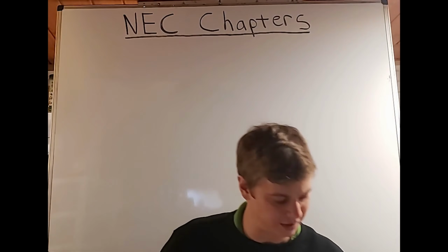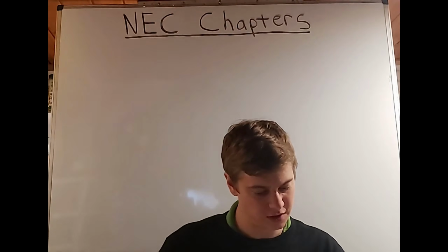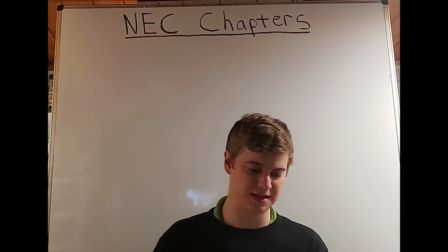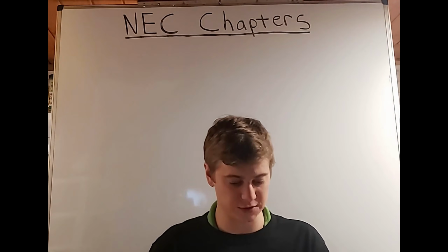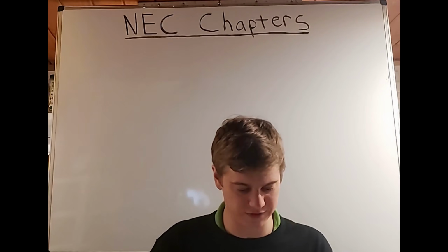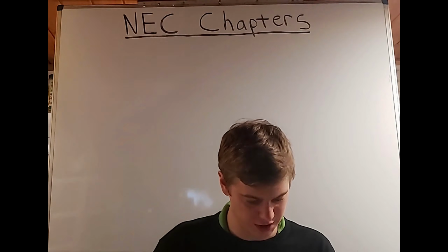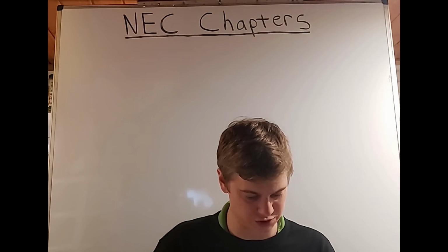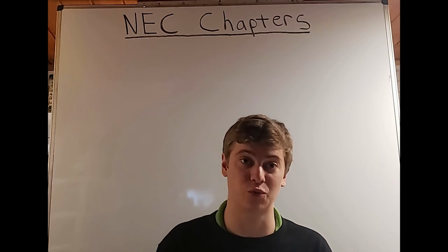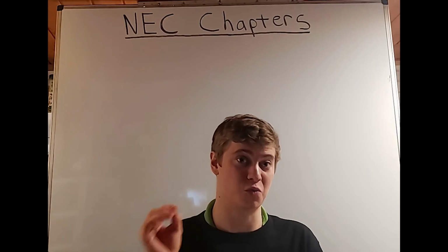Okay, Article 200.4, neutral conductors. We have A, installation, B, multiple circuits. Article 200.6, means of identifying grounded conductors. A says sizes that are 6 AWG or smaller, and it mentions the following means of identification. And of course, this is the insulation. Okay, so you can have: 1, a continuous white outer finish; 2, a continuous gray outer finish; 3, three continuous white or gray stripes along the conductor's entire length. This is allowed on other than green insulation, okay? Because again, green is going to mean grounding, and we're talking about grounded, we're talking about neutral.